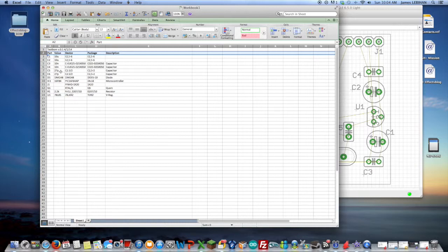Here's the value for those components where we have them, the device type, and the packaging type. And this again is going to be very useful for us when we're looking at purchasing the parts, and we can update extra information in there too. And then this says what type of component it is. For some reason it's missed a couple of those, so we're just going to add those in there, and then we should be pretty much good to go.